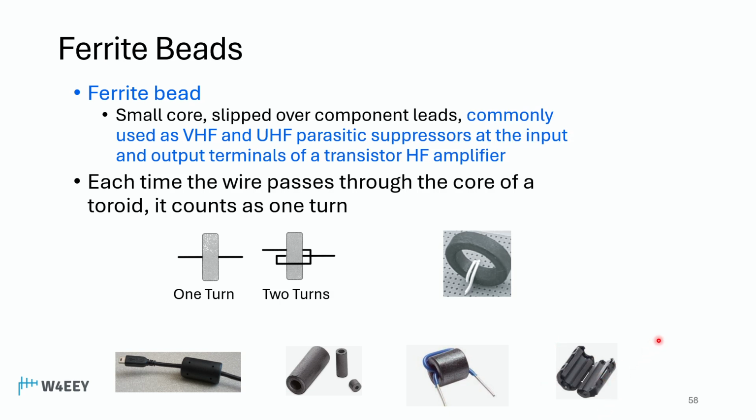I'll give you my story first, and I think Gary has one too, but we'll do mine first. I had a keyboard that, anytime I was transmitting, wouldn't work. So if I was trying to type in a call sign in my logging software, I had to wait till I stopped transmitting before the computer would take the keyboard presses. It was a wired keyboard, so I put ferrites on both ends, and it solved my problem. I know Gary used to operate out of a second floor ham shack, and I think ferrites are your friend too, right?